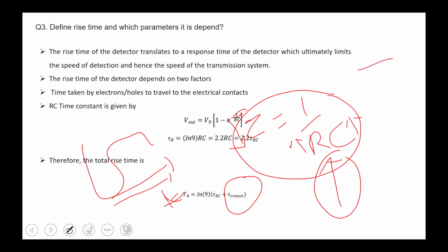In the semiconductor, there is a conduction band and a valence band, and between them is the EG, our band gap. So the electron hole pair will be generated and reach the conduction band, and there we have to collect from the conduction band only. So the time taken for that is the transit time.